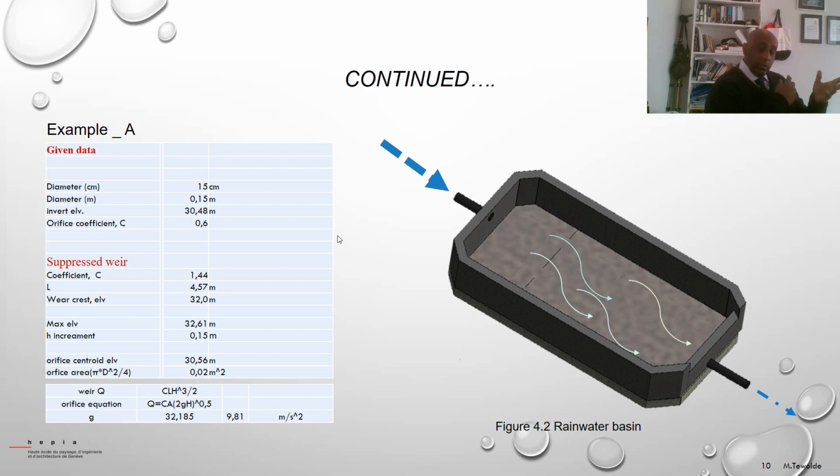We need to have some data, for example, the inflow hydrograph, the hydrograph that is coming. This might be recorded at the spot. For a certain period, we establish some kind of measuring device to measure the hydrograph at the entrance point.